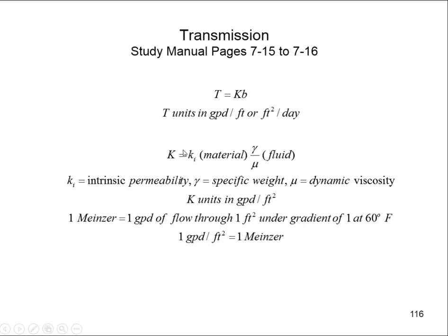And then this section here is a reminder that our hydraulic conductivity is based not only on the material, clay, silt, sand, gravel, but it's also based on the fluid. When we have water, we tend not to think about the water. We think geologically, think about the material. But if we have contaminants, are those properties of weight and viscosity greater or less than water? That's going to act a little bit differently and impact the hydraulic conductivity of those materials.